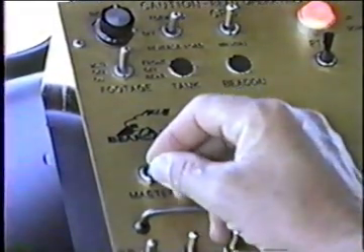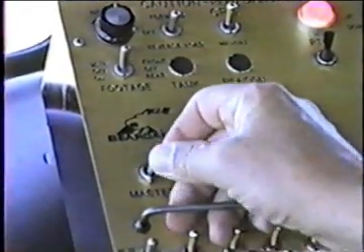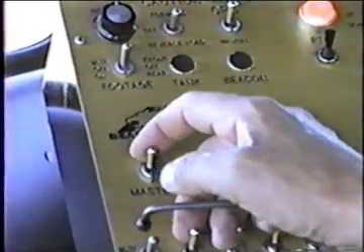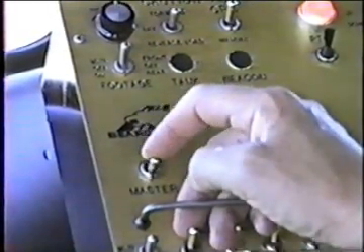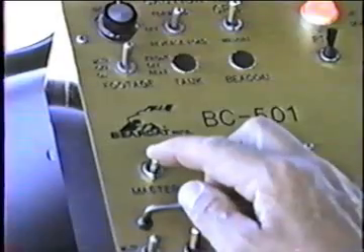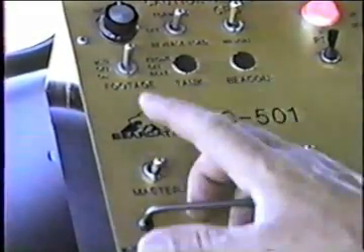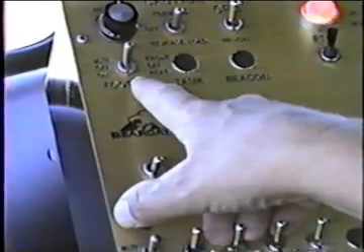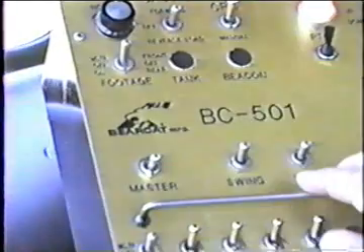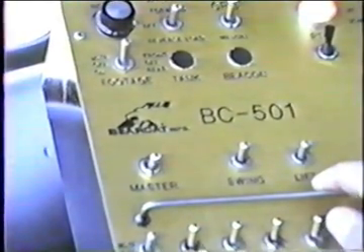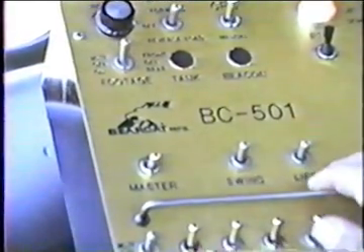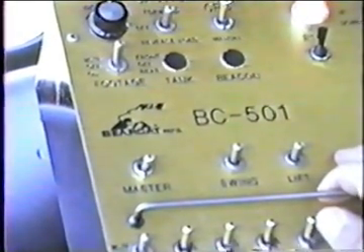So that now when we turn the master switch on, the truck opens up and the footage meter turns on. When we turn the master switch off, the spray bar shuts off and quits measuring the distance. That's so that it shows us just the spread distance. From that we can calculate to see if our spread rate has come out right.